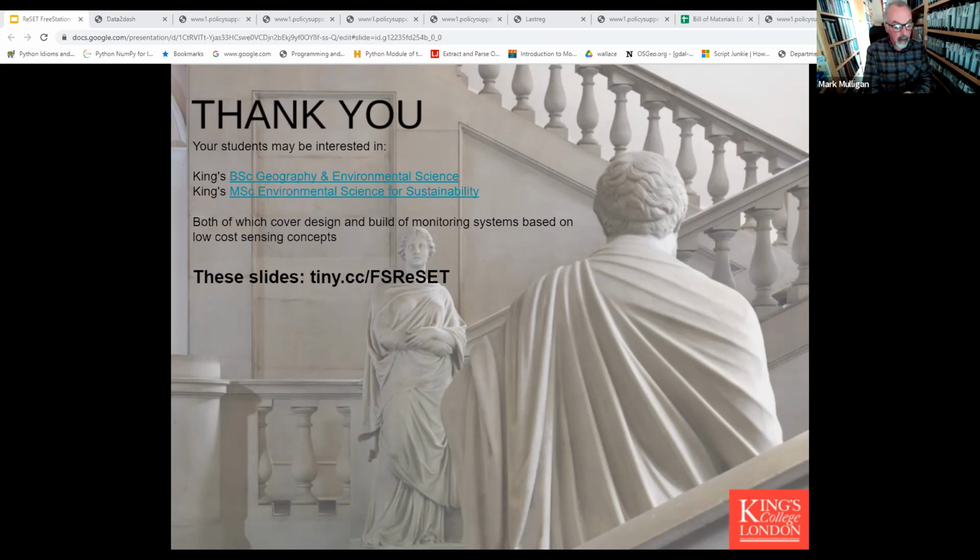Another element is calibration. Some instruments, particularly pressure sensors, their calibration changes over time. The fact that we use cheap ones means that you can replace them manually if you want, and that's not going to cost a great deal of money. They're just a few pounds each.